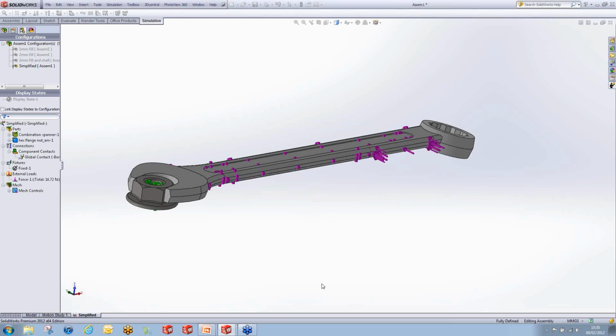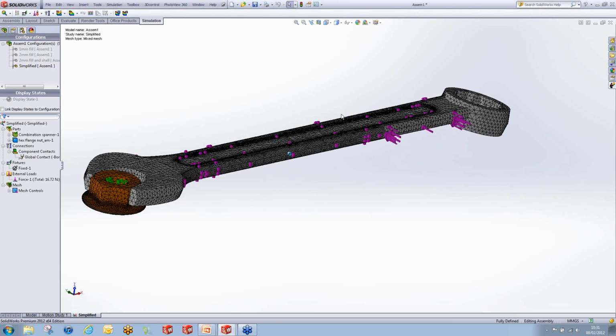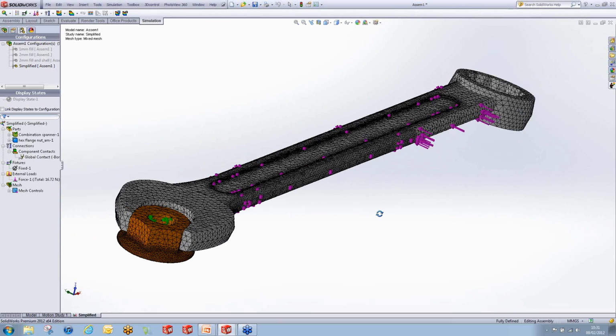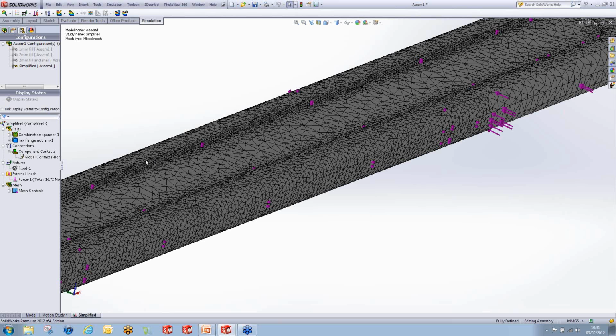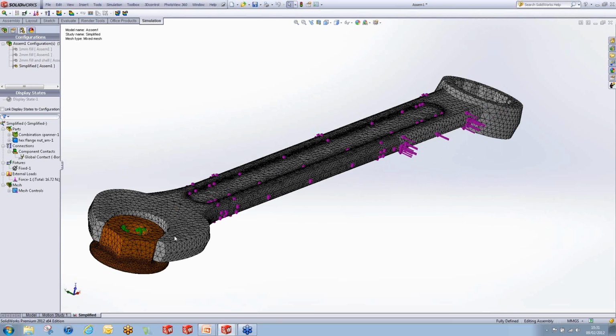It's very simple, and if any of you have experience using more advanced FEA tools, you'll see how simple the meshing process is here, and that's really nice, and that really takes away the complexity of the process, making it more accessible for everyone. The idea is that every designer can run these simulations with relative ease. So having a look at the mesh now, we can see that specifying those mesh controls in these areas has made it much finer, and we can see that where we haven't specified those mesh controls, that 1 mm mesh size has been applied.